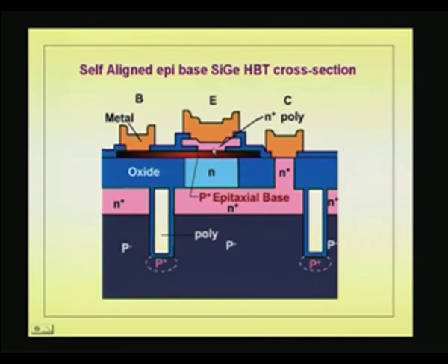Okay. This is another thing which is very attractive for self-aligned techniques, and also you put an N plus contact, which slightly diffuses into this region and makes a single crystal, very shallow N plus or N type junction, and then a contact is taken onto this N plus layer. Okay. So, this is the structure here. And of course, people use techniques from silicon technology for trench isolation, etc., where you put a trench, oxidize it, and put polysilicon. All those techniques are there for isolating devices in integrated circuits.